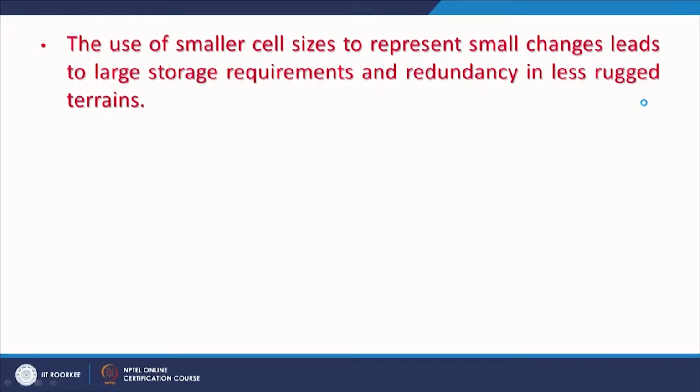Though by employing higher spatial resolution data or small cell size data, that means representing a small ground area or field area, we can definitely go into much more detail. But if we go for higher and higher spatial resolution, though our requirements may not be for that kind of resolution or scale, then it will be unnecessary, redundant, and it will require large storage space on your storage devices, and it may create some problems in future.